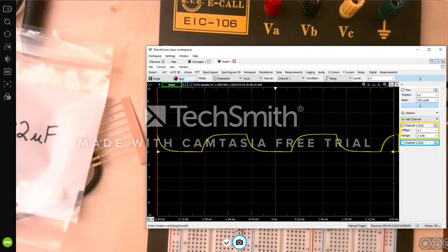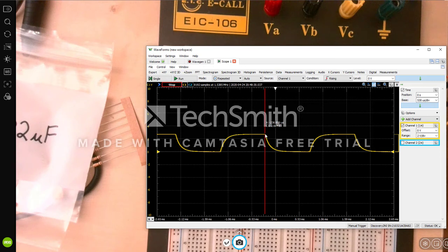Okay, so here we have our waveform of the VC, the capacitor voltage. Let's stop it at a given point and see how it behaves. Again, it starts to charge up at the start of a given period, and it charges up to a value of roughly 2.68, which is lower than the previous part, as you're supposed to find in your calculations.